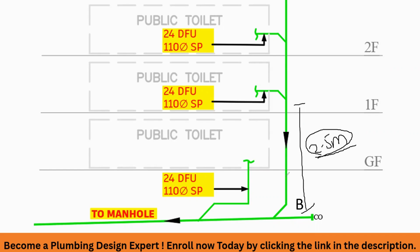And if you are getting enough space below the ground, so that you can give 2.5 meter below, in that case you can connect. But in most cases you will be taking a pipe just below this, so you will not get that much space. In that case, it is better to connect this ground floor public toilet to the building drain, not to the vertical stack.